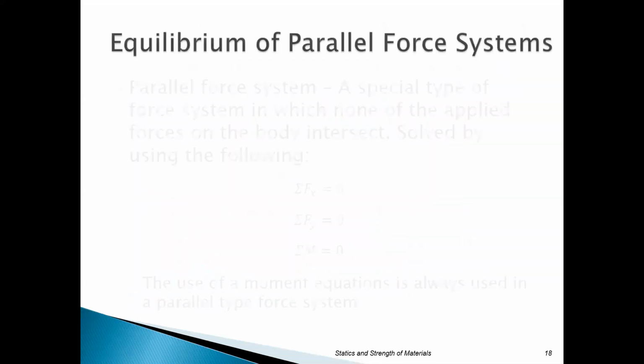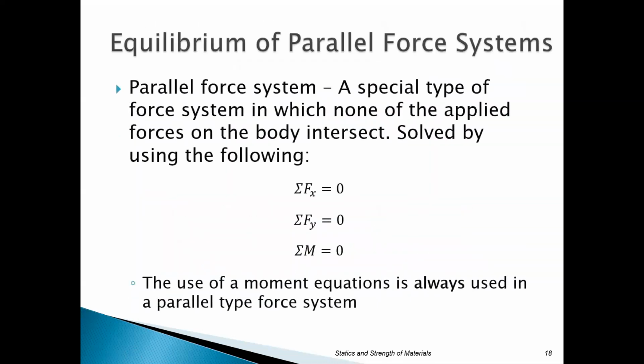We've already talked about this. So, all right, the parallel force system is a specialized type of force system. We use it a lot on beams and floors and roof design. But you always are going to use the three equations of equilibrium. Sum of forces in X, sum of forces in Y, sum of moments. And moments are usually going to give you what I call the distribution of what's happening between your reactions.